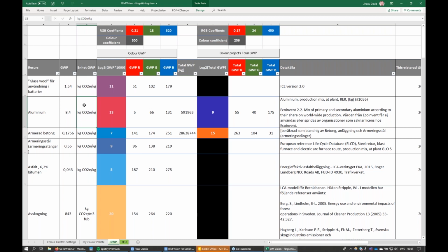Now, some analyses I've seen communicate the carbon footprint per square meter. That's in the case of doors or windows, but it can also come in cubic meters in terms of concrete and so on. So you really have to be vigilant about what functional units are used when you're working with carbon or any other type of environmental impact.